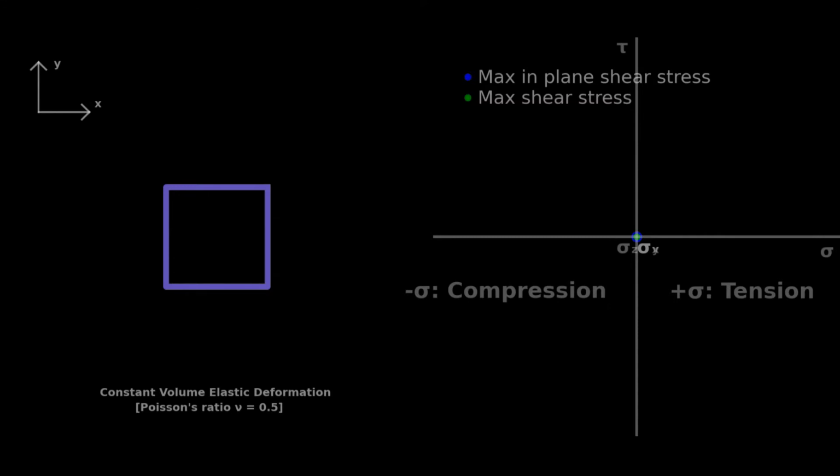The Poisson ratio defines how an element will deform, shrink, or stretch in the axis not subjected to a force. I only include it to make the animation clear, as you will see the material change shape as forces are applied to it. The Mohr circle will be graphed on the right. The graph x-axis represents the normal stresses, denoted as sigma, and the y-axis represents the shear stresses, denoted as tau.